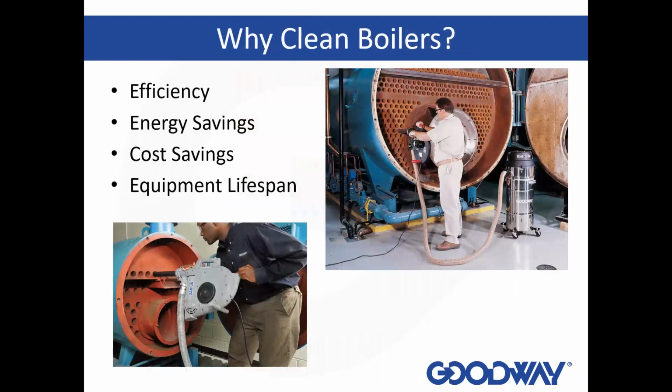So why are we cleaning boilers again? The efficiency and how much fuel you're burning is tied directly to the heat transfer of the vessel. The more buildup that you have on either the inside of the tubes or the outside of the tubes is going to affect that heat transfer.